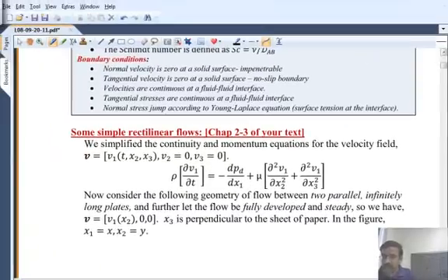And in the last lecture then, towards the end, we started developing solutions. So the rest of the course is going to be about solving these sets of partial differential equations under various conditions, subject to the typical boundary conditions and initial conditions that we will see. So the first problem that we started analyzing in the last lecture is the so-called rectilinear flows. Flows in which there is only one velocity component and the other two are zero. And that particular velocity component could depend on time and two perpendicular coordinate directions. Okay? But so it can vary in the direction perpendicular to which it is pointing.